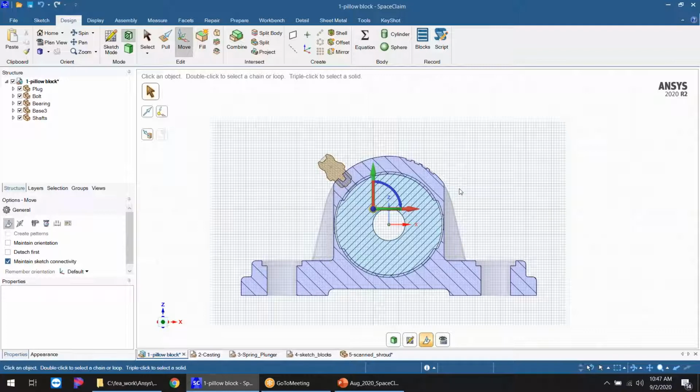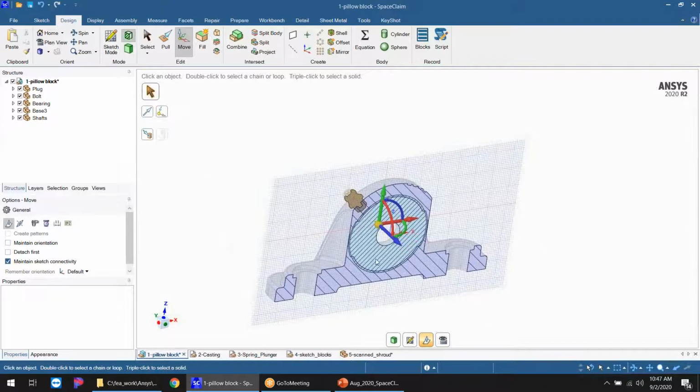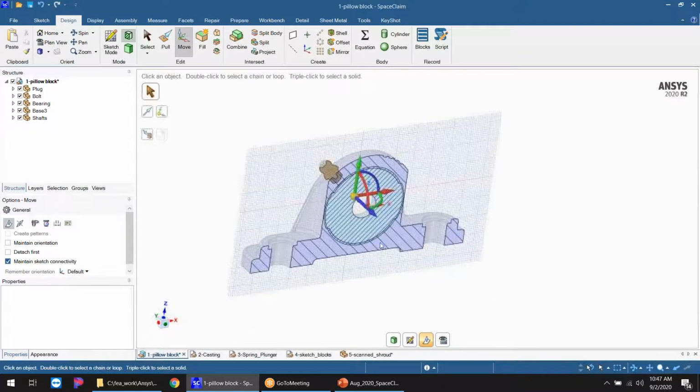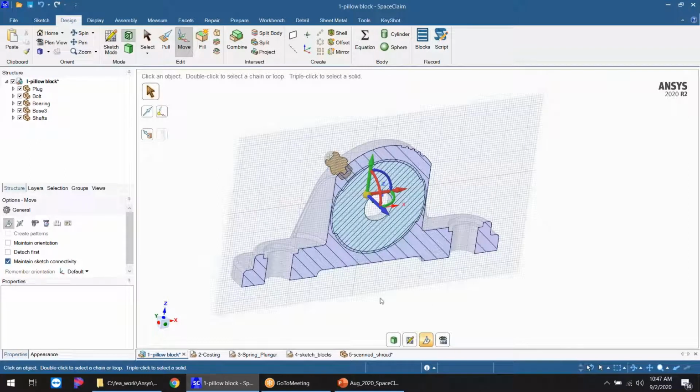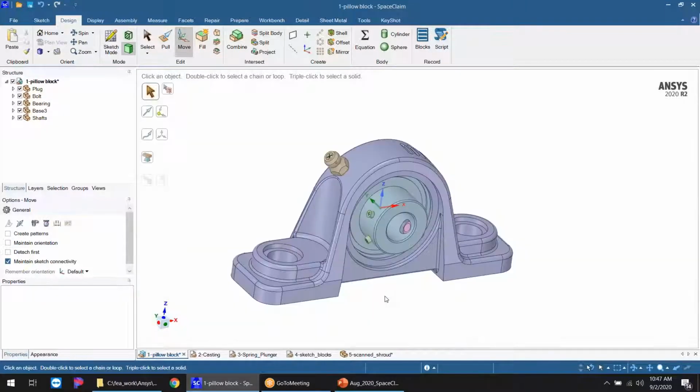And I can see, do I have any interferences? What do I have for parts? Where are my assembly parts located? It can correspond to where everything is in our structure tree over here. So that's the shortcut to the cross-section tool, very important for looking at assemblies. The larger the assembly is, the more complex it gets. I can get back to my 3D mode using this icon here, or by just hitting D. So X and D toggle back and forth.